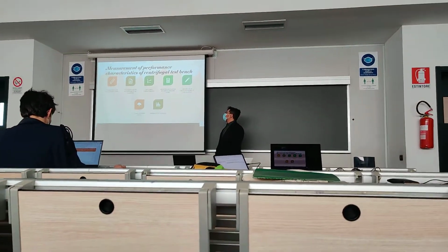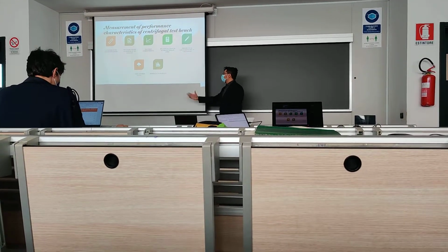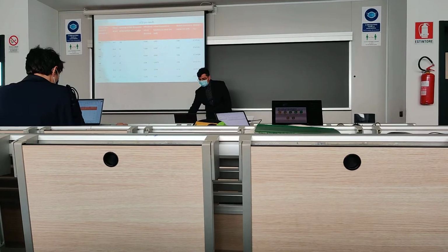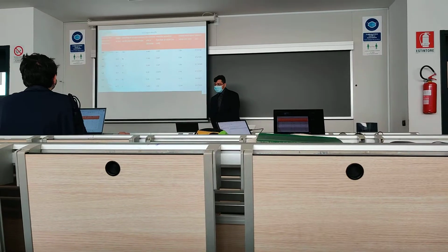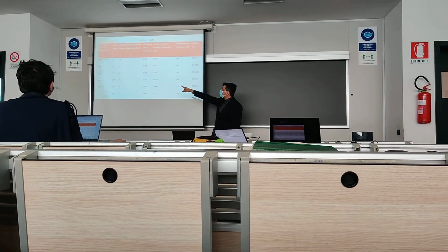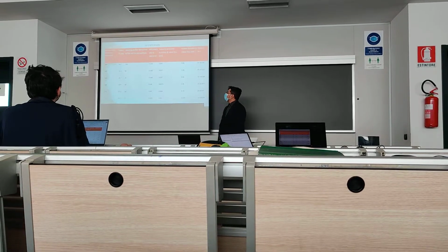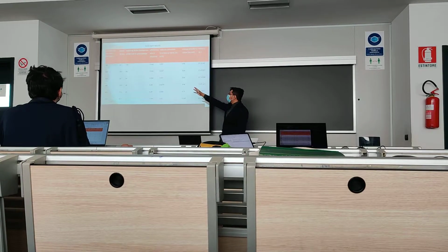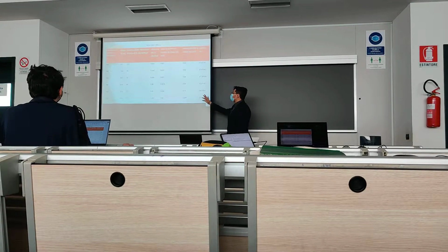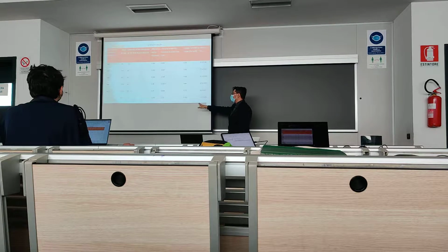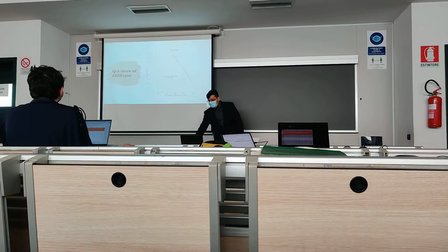From that we can calculate the velocity and pressure values, and I did it for 5 different speeds, and we can see the influences. This is a particular result from one of the RPMs. You can see a trend that the mass flow rate decreases when you pressurize it more and the head increases when the opening of the damper is closed completely, and also the efficiency increases. The velocity potential function and the stream potential function remain almost the same, and for a fully closed case it slightly changes.